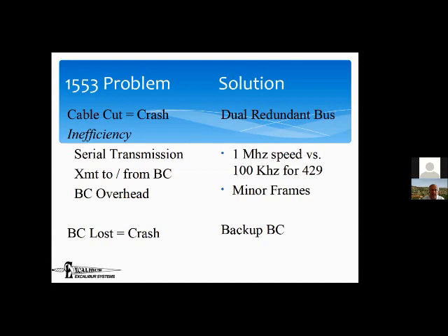Okay, and then in addition to the fact that it's serial, there's a lot of extra overhead on a bus, right? Anything that the bus controller says, since there is no bus controller on other types of buses, so all of the bus controller transmissions are overhead, which you don't have in others. So in order to deal with that, we have this notion of minor frames, which is an efficiency issue, which we're going to get to in the timing section of the course.